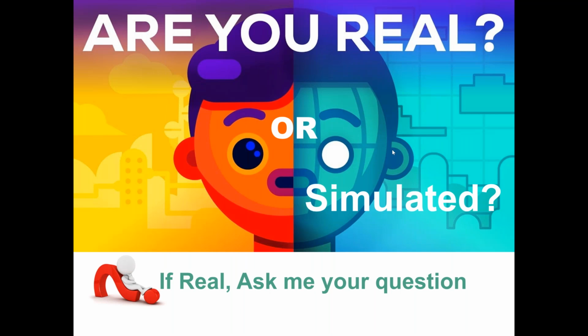They can be EnergyPlus, they can be, for example, Florida has IESVE, DC has EnergyPlus, IESVE. We have to go over the local guidelines. But for a single building, yes, we have to use the same energy modeling program for baseline and proposed. We cannot use two different things.